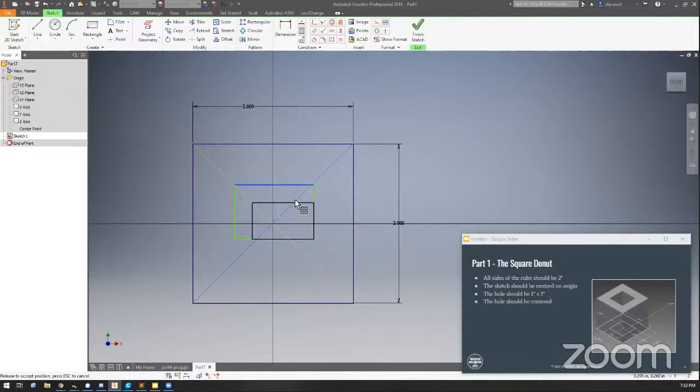It makes sure that no matter how the other parameters of this square change, this corner stays on this construction line. As I move this down, you can see that corner tracing along that construction line. That's great, that's what you want. The second thing we're going to do is use the dimension tool to dimension one side of it and say it's 1 inch. Then this other side we also want to make 1 inch. So now we're getting closer to having this thing constrained.